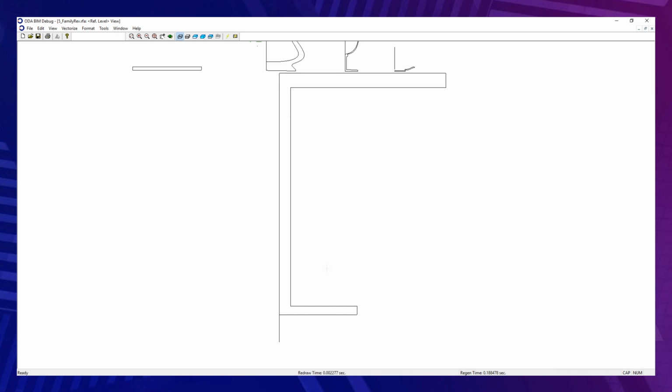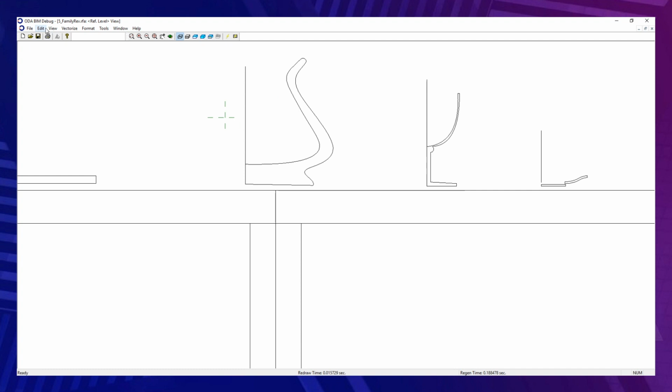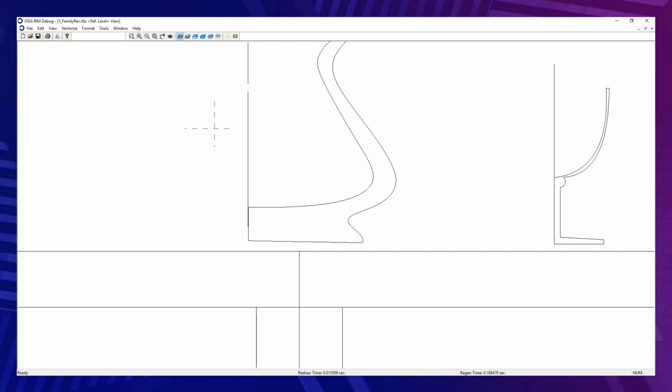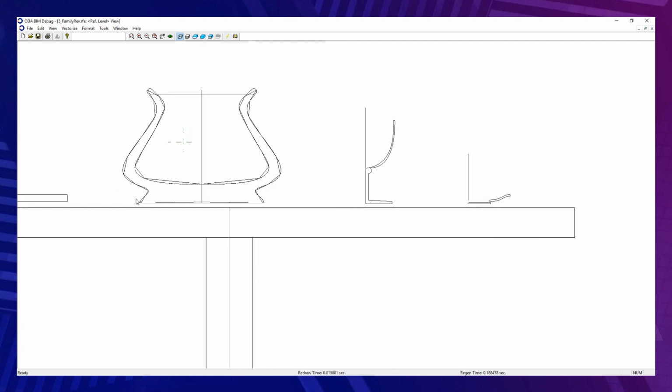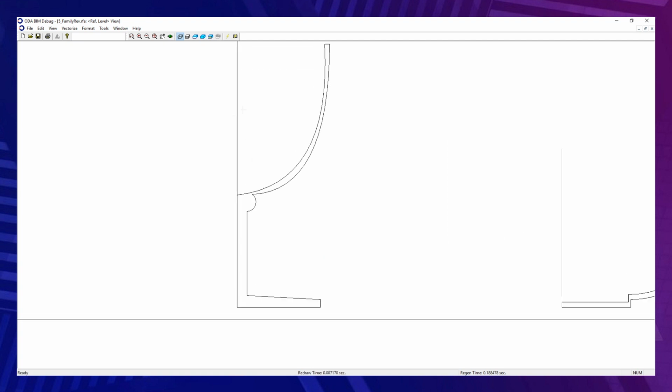We select the loop, we select the axis for rotation, the start angle, the end angle, and select the material for this element. So one element was created, and here are several more examples of revolution elements. So we also select the loop, select the axis of rotation, and all parameters needed for this element. And a couple more elements, and after this we will see the result in 3D view, for example, because we created them in 2D view.